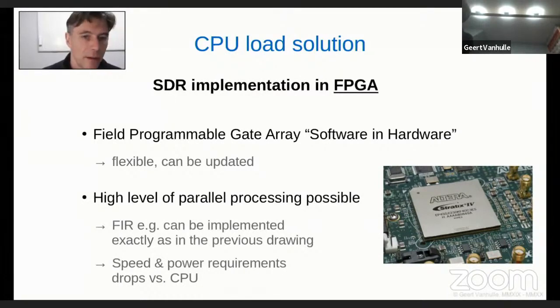Of course, there are already FPGAs built to mil specs, but also what is a possibility here is to integrate sections into the FPGA that are optimized, for example, for the AD converter stage, like a mixer stage in digital form, or for example, predefined FIR filter stages. So it's possible to create FPGAs that have certain physical blocks inside of them that are predefined and connected inside the FPGA, which can create a far more interesting chip to use in an SDR setting than is currently on the market. So that's an opportunity here for somebody who would be interested in it.